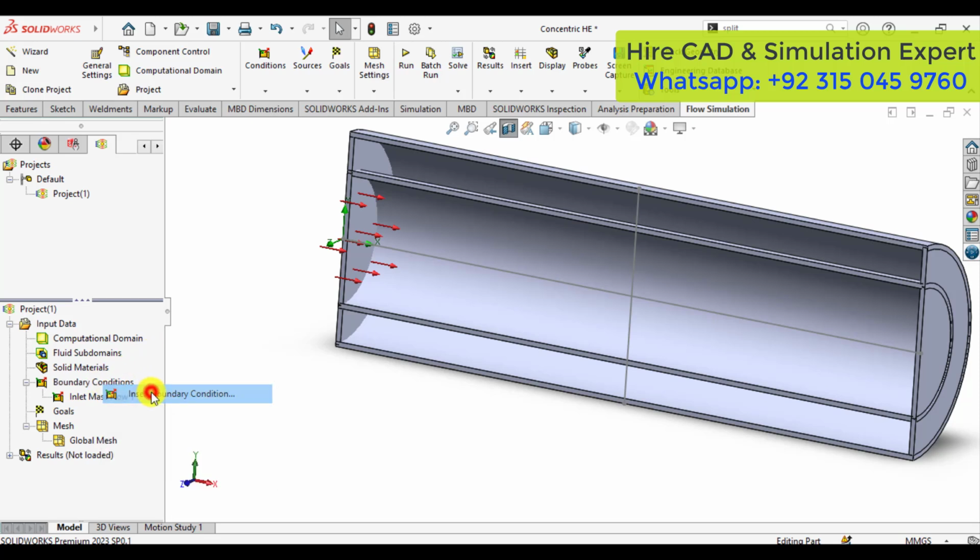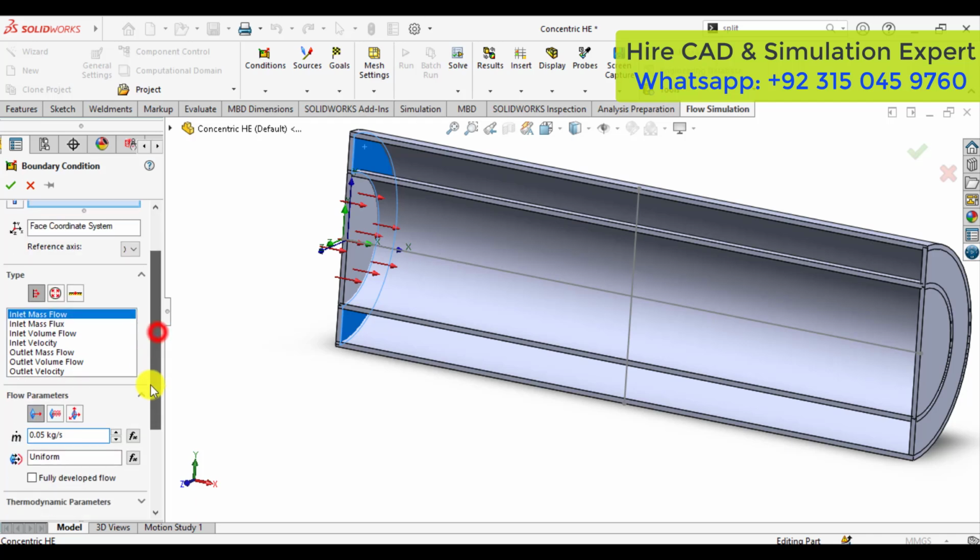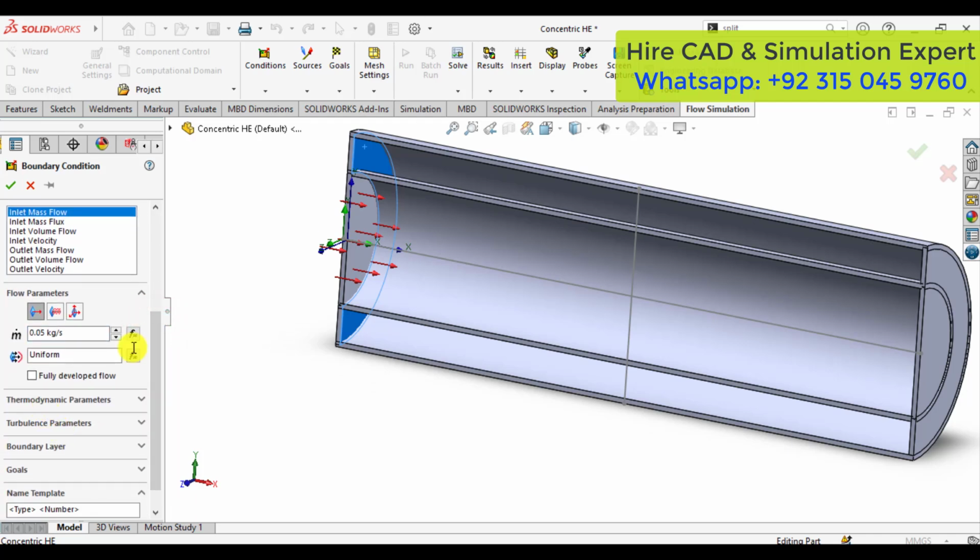Again, go to the boundary conditions and select this face. And the flow rate is 0.05, while the temperature of the hot fluid that is flowing on the outer side or in the outer tube, that is at 350 Kelvin.